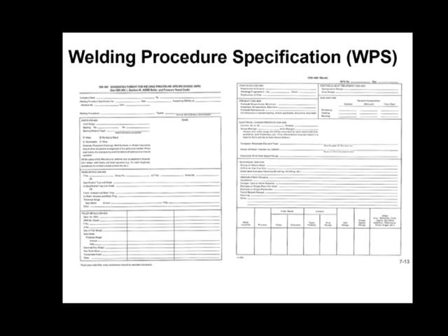One of the problems with welding procedures and PQRs is that people that aren't really initiated into the craft end up thinking they have to fill in every blank on the WPS or PQR. You don't have to fill in every blank. You just need to look in the code and address the essential and non-essential variables that apply depending on what you've got going on. On a WPS, you have to address essential and non-essential, and on a PQR, you just need to address the essential.